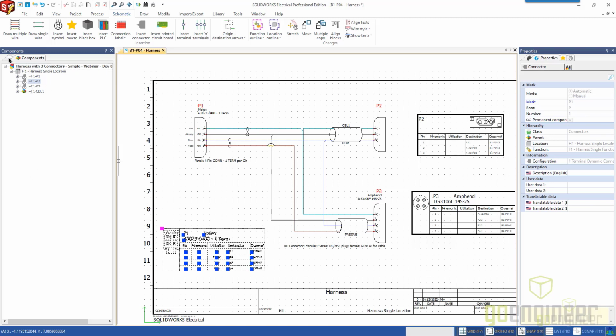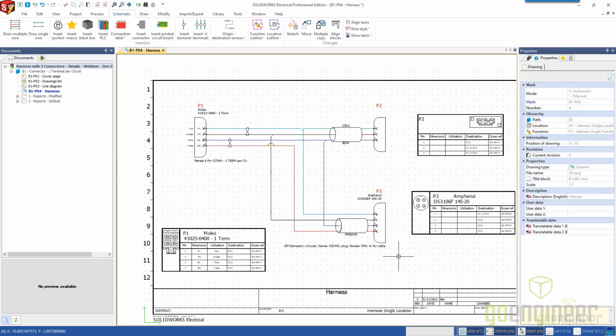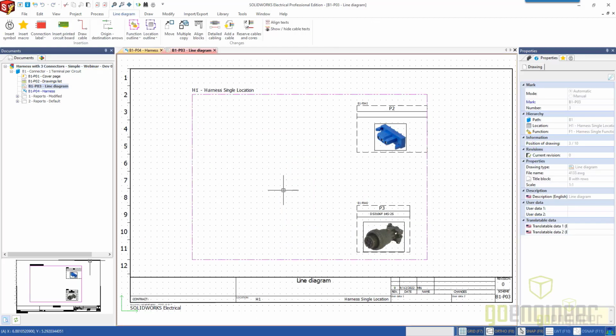I need to take a moment here to jump back over to my single line. So this is describing a harness, or what will be a harness, in multi-line or a schematic page. You can also describe the information in single lines. Single lines, again, I like to combine those. So a single line is for those that don't know how to read schematics. The multi-line is for those that know how to read the schematics, or those that are doing the production of it. So same basic idea there.